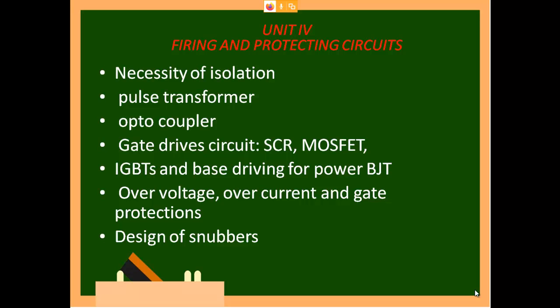If there is any leakage in this, it will be transferred to the source side. Source is nothing but your gate. So automatically the gate will be unable to withstand this very high voltage, because it has been connected to a microcontroller whose power supply is only 5 volts. So the entire circuit will collapse. What is required is an isolation between your pulse and your drive circuit.